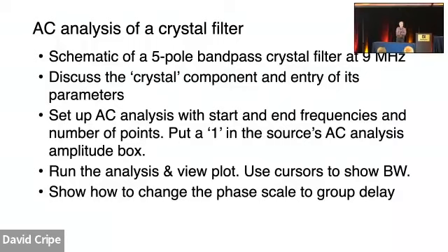In fact, it numbers them that way. That's because internally, a capacitor has series capacitance, series inductance, series loss resistance, and parallel capacitance, same as a crystal. So they didn't need a different model for that. It's just the numbers you put in there determine how it behaves. So I'm going to set up the AC analysis with start and end frequencies. This one's going to be more focused because this is the sideband width filter.